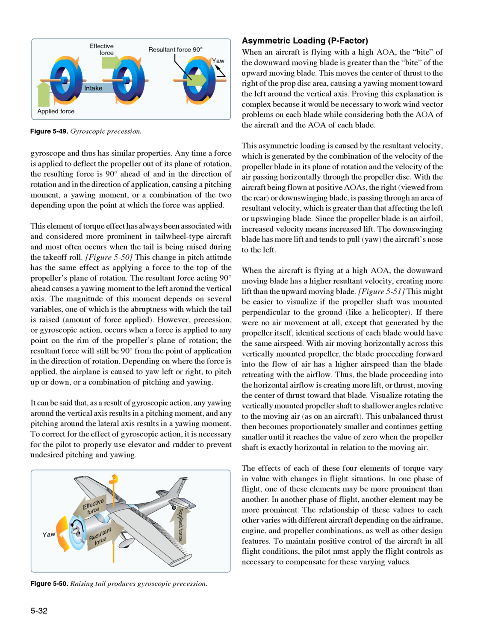The effects of each of these four elements of torque vary in value with changes in flight situations. In one phase of flight, one of these elements may be more prominent than another. In another phase of flight, another element may be more prominent. The relationship of these values to each other varies with different aircraft depending on the airframe, engine, and propeller combinations, as well as other design features.